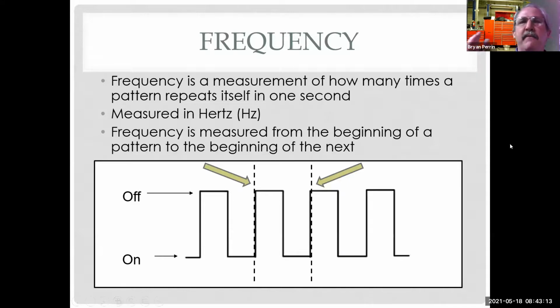If I don't have a lab scope, I may have a digital multimeter that measures frequency. So I could hook up to a wheel speed sensor and spin it and see if the frequency changes, which would at least give me an indication the sensor's generating a signal, and that it's a higher frequency the faster I spin the wheel.